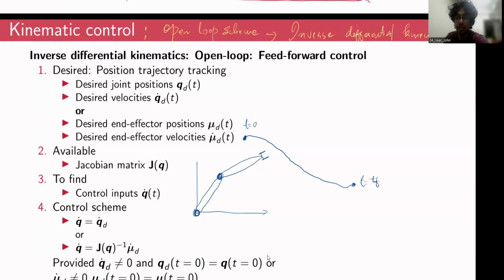For the initial position, I would specify the initial positions and initial velocities in Cartesian space, because that is more convenient for me. We can visualize how the initial position and velocities would look in Cartesian coordinates. So initial position I will depict using x and y at time t equal to 0, and then initial velocities, x dot at time t equal to 0 and y dot at time t equal to 0.